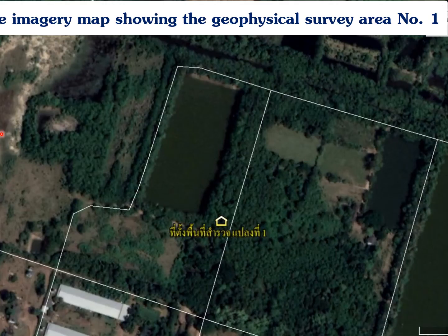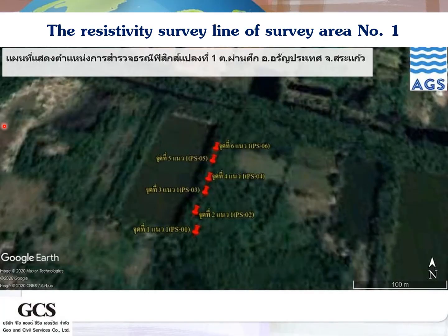This is the satellite imagery map showing the geophysical survey area number 1. The resistivity survey line of survey area number 1 is composed of 6 survey points, with a distance of 20 meters between each survey point. The exploration depth is 20 meters.